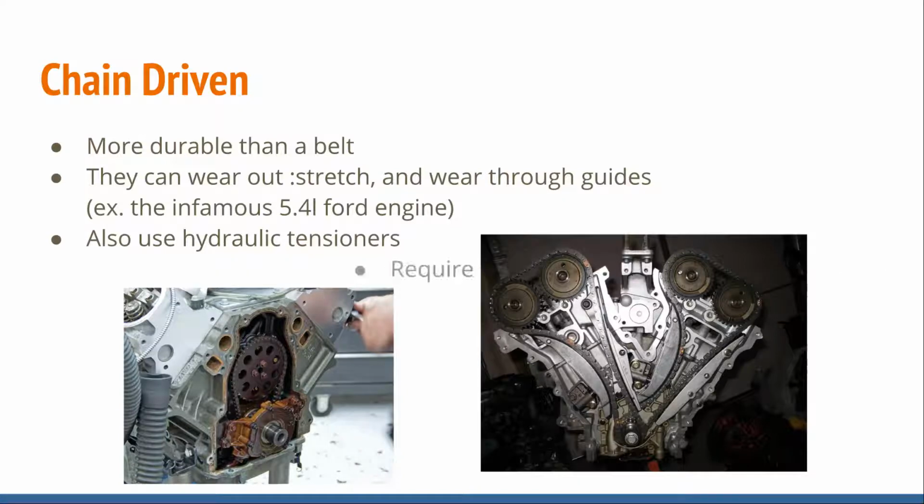Your timing chain requires constant lube. It's always going to be wet. There's no such thing as a dry timing chain. So it's always going to be wet and it's always going to be oil fed. You've got to really keep up the lube on those timing chains.